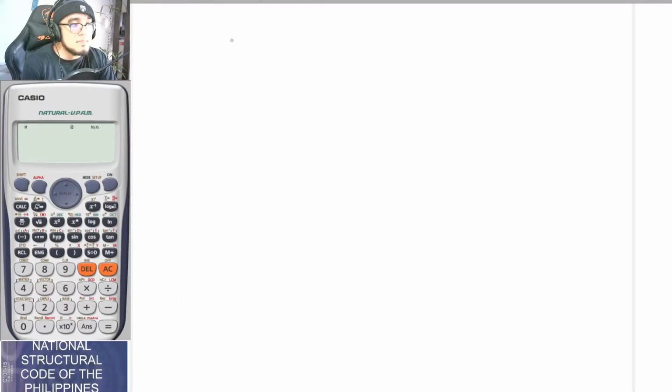So moving forward guys, when we are to be designing a doubly reinforced beam, these are to be the typical steps. Of course, the first thing that you should do is for you to get the loads. And if you would be getting the loads, you would undergo, let's say, the simplified method or other structural analysis subject matter. You just get the magnitude of your moment. And after getting your moment, you would now undergo load factors.